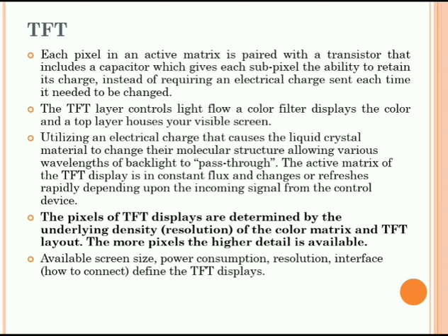The TFT layer controls the light flow, a color filter displays the color, and the top layer houses your visible screen. An electrical charge causes the liquid crystal material to change its molecular structure, allowing various wavelengths of backlight to pass through. The active matrix of a TFT display is in constant flux and changes or refreshes rapidly depending upon the incoming signals from the control devices.